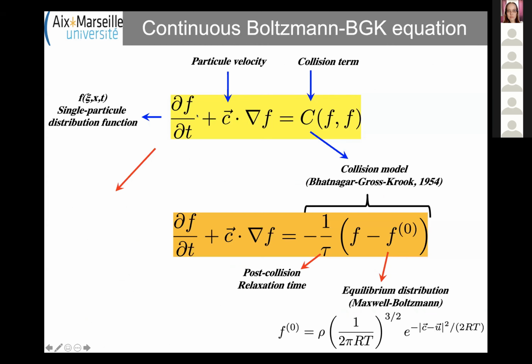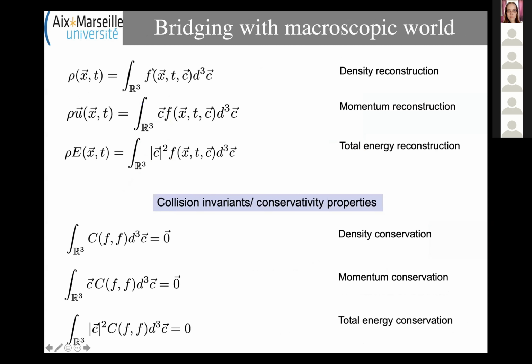The real Boltzmann equation is a continuous equation for a distribution function. What we do is discretize the distribution function space, so the velocity space, in order to minimize the complexity of the problem. And after that, the point is that what we should enforce is that density will be recovered as a zeroth moment, momentum as a first moment, and so on. So the trick is that when you discretize your velocity space, that corresponds to quadrature points in the velocity space for these integrals.